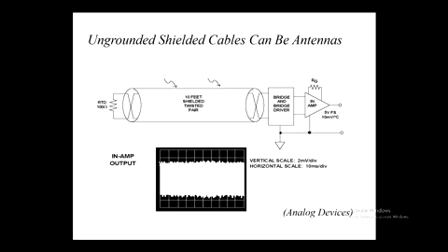If there's no pathway from here to connect to ground, you'd want a wire or some capacitor or something to connect between those two points. Otherwise, it's just a collector for interference to re-radiate into the signal lines. So, think about it. It has to be done, otherwise it's not worth the effort in the first place.